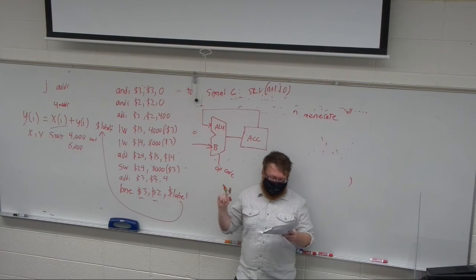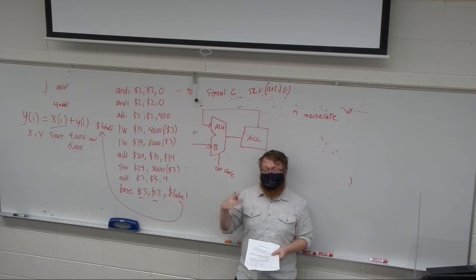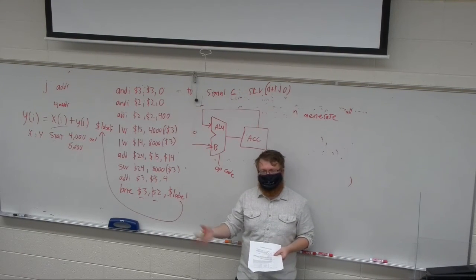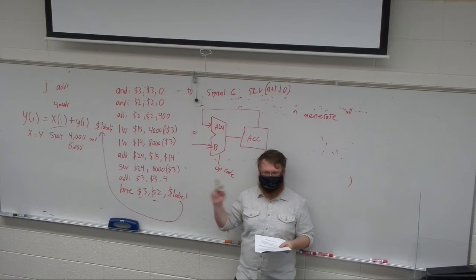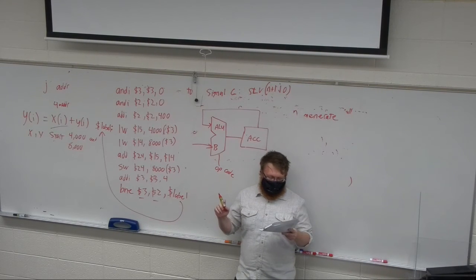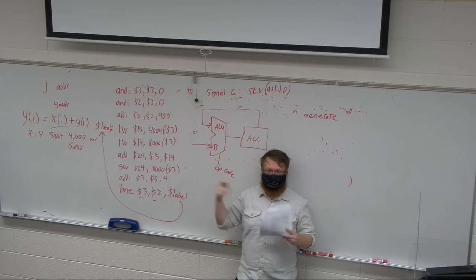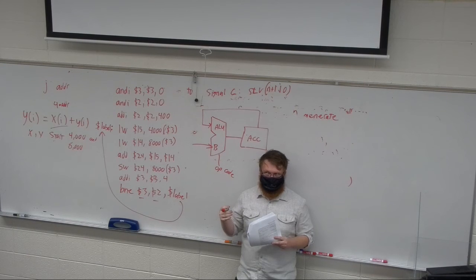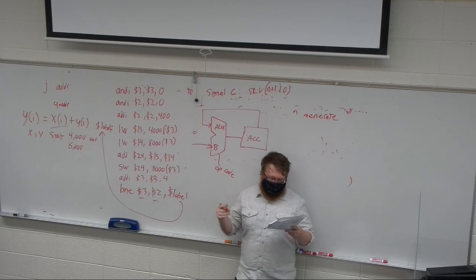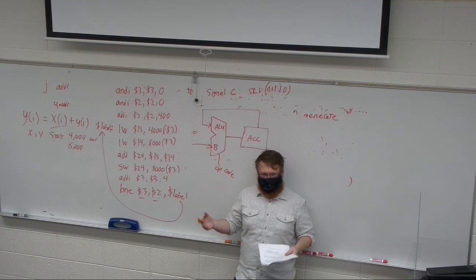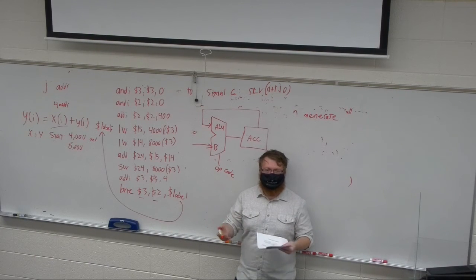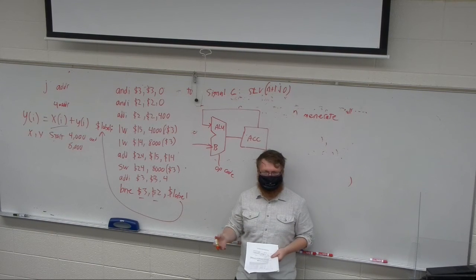And then you're going to have 5 bits that are generally unused, which are your shift bits. If you want to shift by some amount, it's stored in that, so you can shift by up to 32. Then they have 6 bits that are extended function code. These are used because some things are not able to be described by just the initial 6 bits.